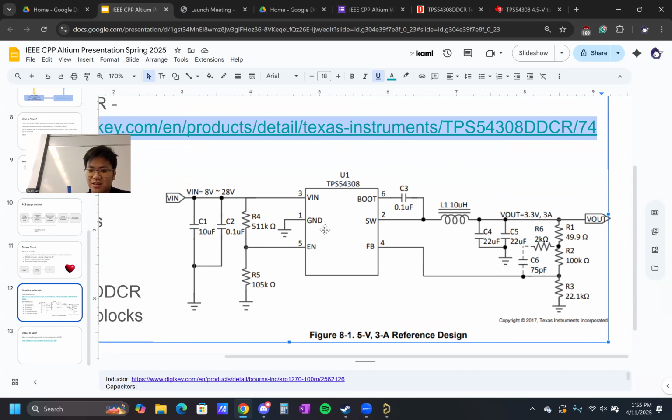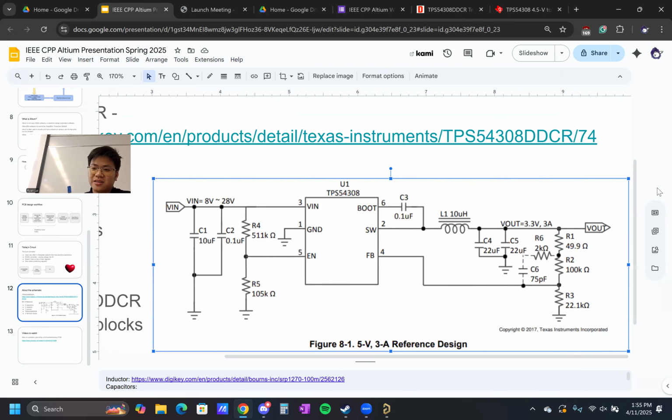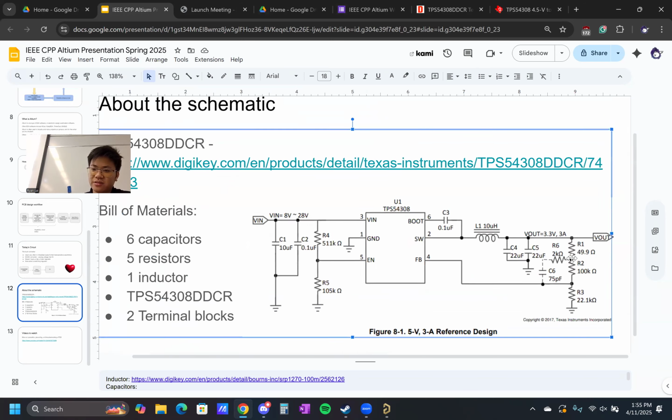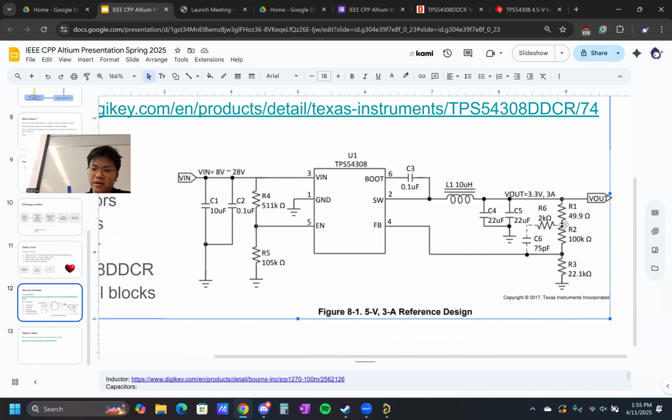So a lot of the circuitry, mainly this inductor here, actually manages a lot of that current flow. If you're familiar with inductors, they're very resistant to current change. So when you have that sharp drop in voltage, it's able to balance it out, depending on how you value it. We're valuing it like this. This is for 3 volts. This is a 3 volt guy.